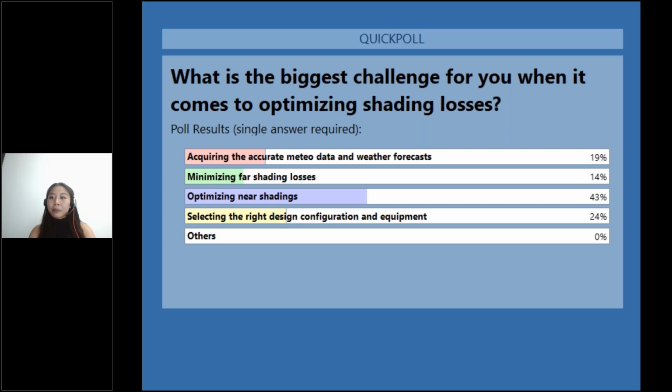So the software PV Design will automate the engineering of your projects. We provide you the TMY data for the local meteorological conditions, and then we also give you in-depth energy yield analysis for the far shading losses, near shading losses, and for east-west facing structures, we give you the option of MPPT tracking. All these factors will take a part in the shading losses in the end, and let's have a look at them one by one.